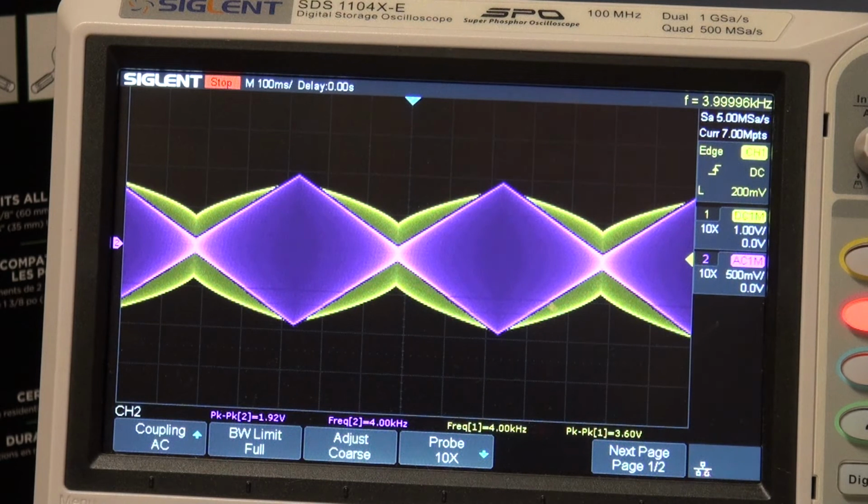Maybe for a final implementation in the ultrasound listener, between the microphone preamplifier and the modulator, the doubly balanced modulator, the MC1496. That's where it will go, and you might need a few tweaks of components. Maybe we don't want an output that is 6 volts or 4 volts maximum.